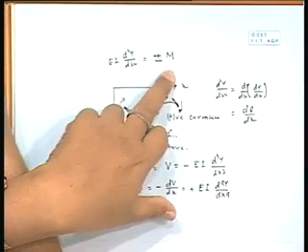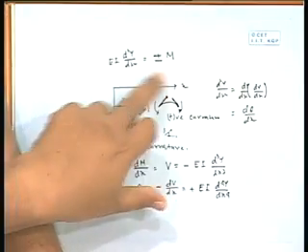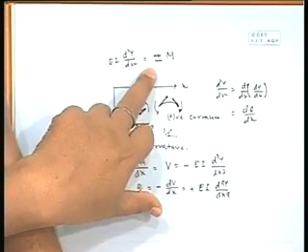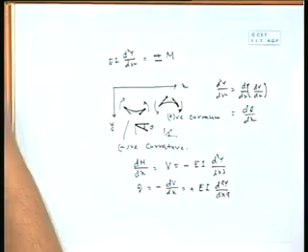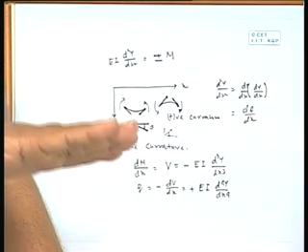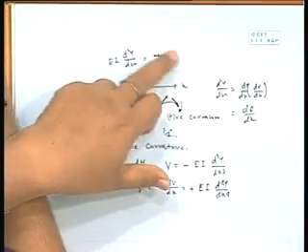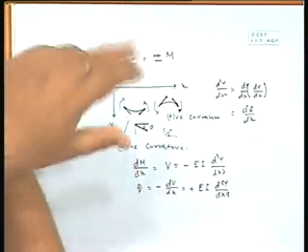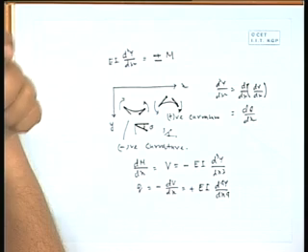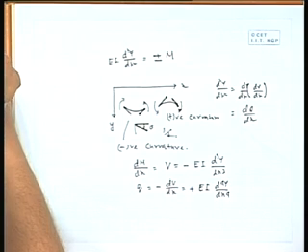Now, in connection with our primary theme of today's discussion, which is deflection of beam, the first line on this page, that is the moment curvature relation EI d2y dx square equal to plus or minus M. With that we will try to solve deflection of beam using the differential equation technique, because this is the differential equation, and that differential equation we will utilize for finding out the deflection of the beam.